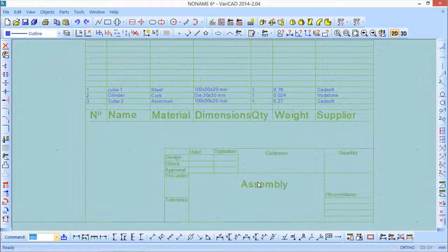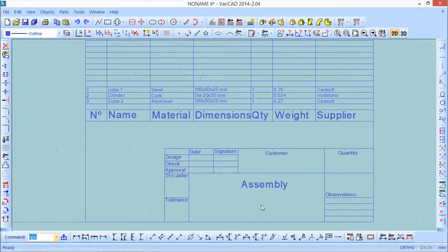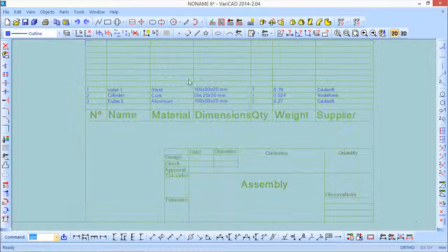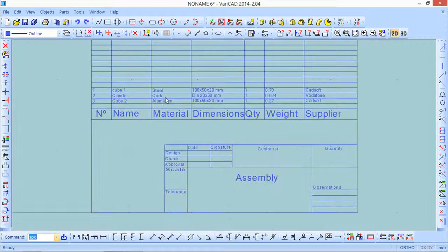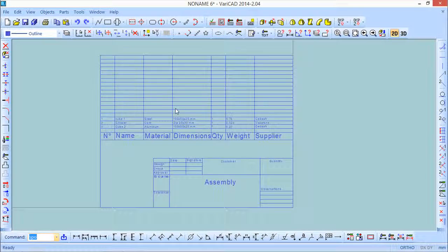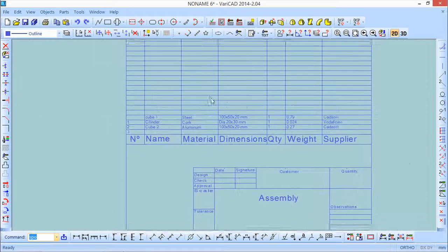I hope it was clear, especially this notion of working this as a full title block, or having this as a title block and the remaining entities inserted as normal entities. Because if we do it like that, instead of creating new parameters with new names, we could use some of the parameters that we have already inside that list and came by default with the installation of the system.